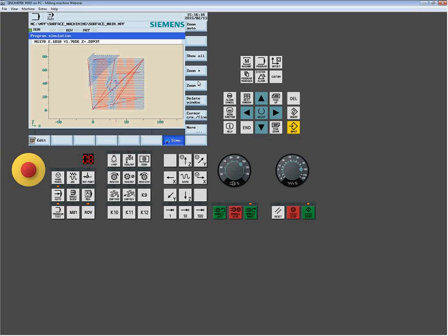There, it just jumped over to the other one. Then you'll notice as it gets down past this one, it's going to even jump into the finish cycle. So you still have all that capability you had before. So there we're into the finish cycle. It's rolling around it. It's a great way to let it run through just to make sure that there aren't any errors or problems prior to physically running the part program.